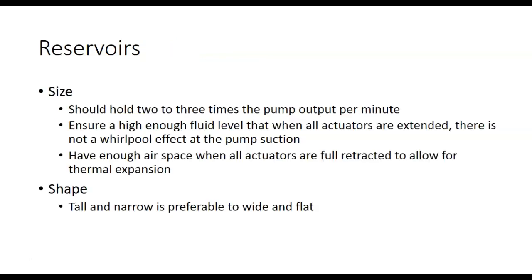Let's see. The reservoir should hold 2 to 3 times the pump output per minute. Ensure a high enough fluid level that when all the actuators are extended, there's not a whirlpool effect at the pump section. Because if you see a whirlpool, what's it sucking in? Air. And air is compressible. Anybody had to have their brakes bled on their car?